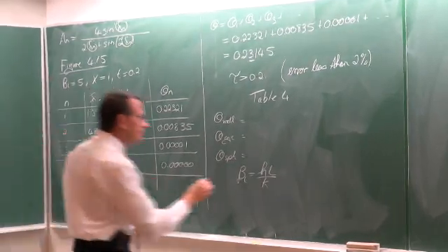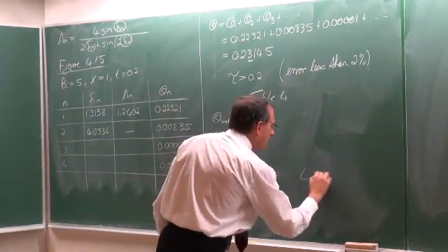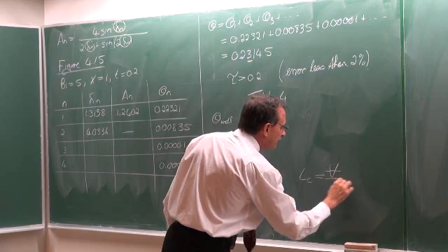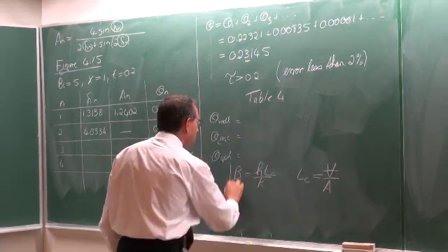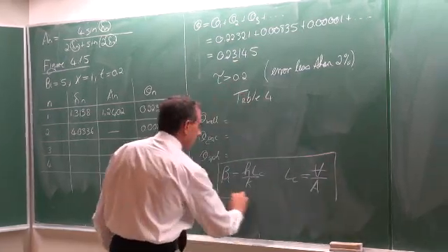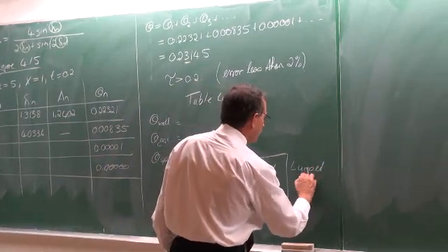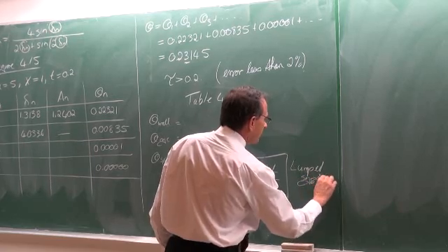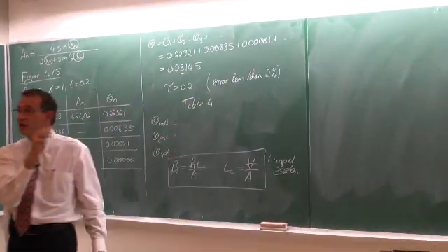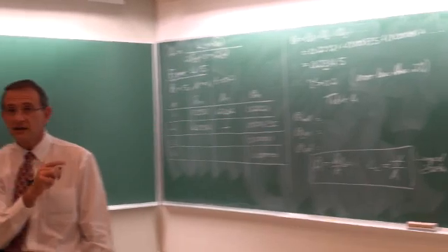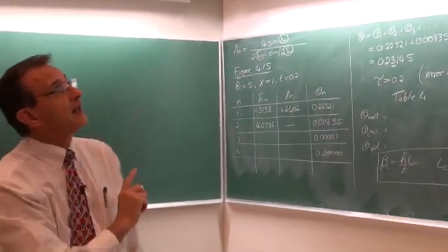The L is not equal to the volume divided by the area as in the lump system approach. Okay, so this is only valid for the lump system approach, not for the Biot numbers calculated here. The Biot number calculated here is as defined there in the table.